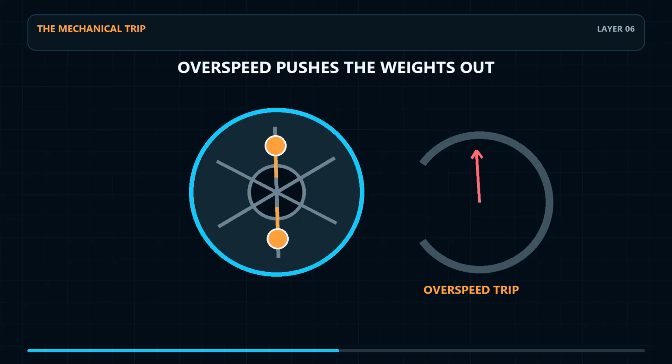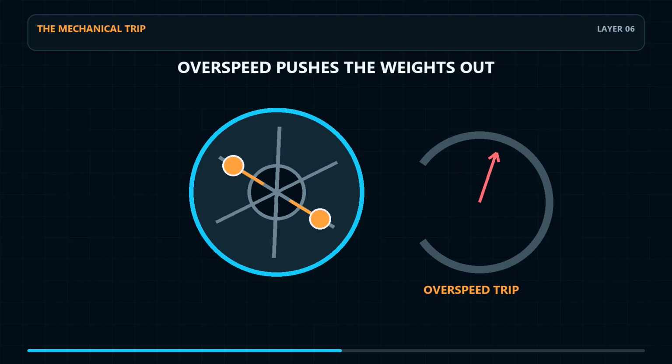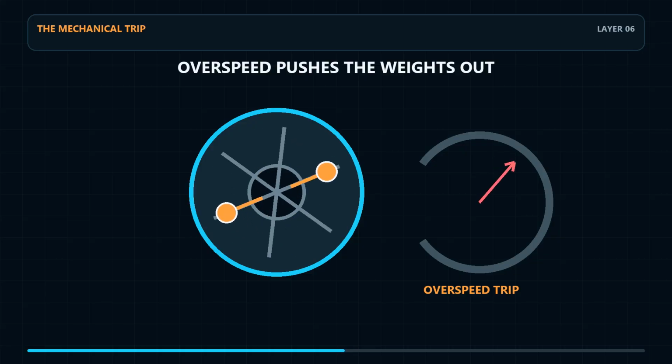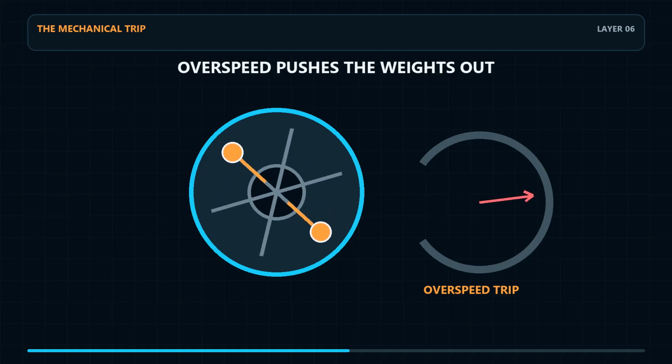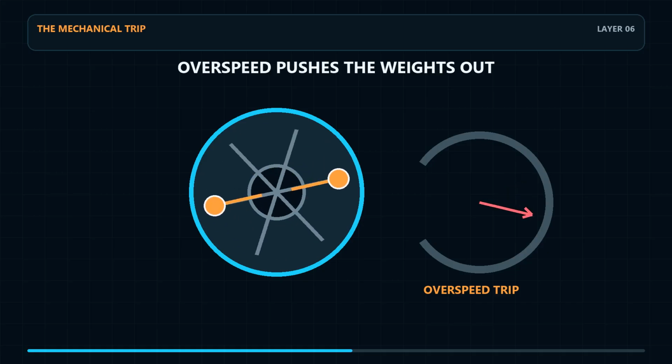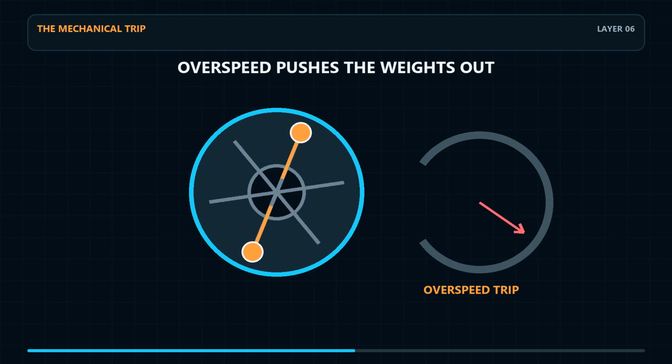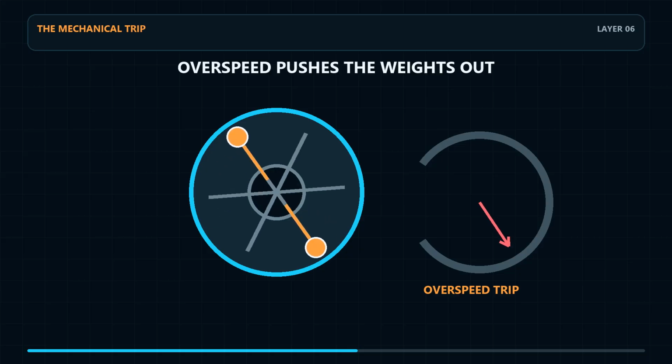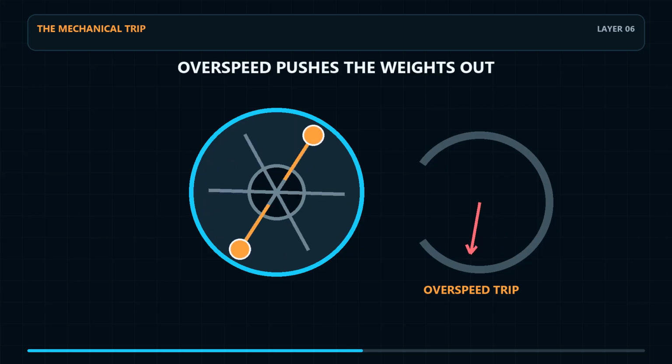At a preset overspeed, the governor opens the safety circuit so power is removed and the machine brake is applied. If the car still accelerates to the mechanical trip point, the governor moves from warning the system to physically gripping its rope. The electrical intervention therefore precedes the final mechanical rope grip action in this sequence.